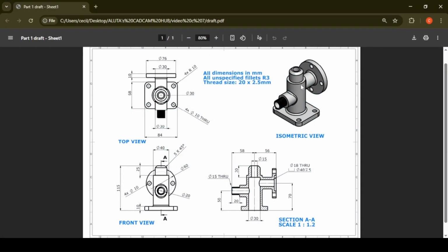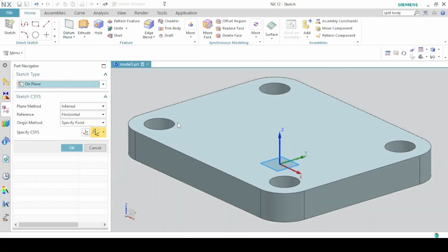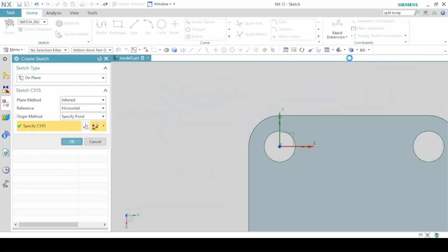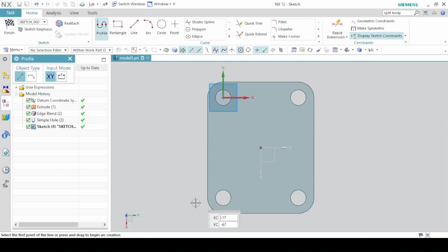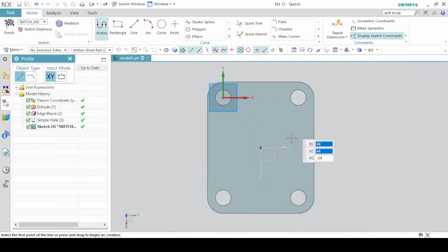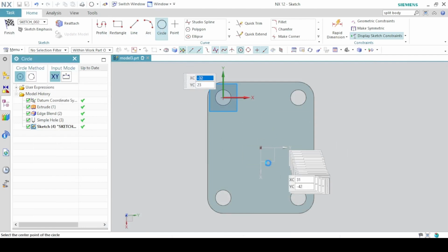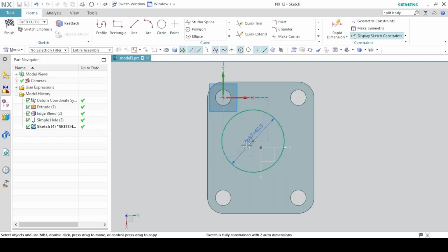Next we add this middle cylinder and the top one as well. So extrude, because we are adding material. Sketch section on this face. So draw a circle of diameter 40 millimeters, and it should be in the absolute center of the block. Let's place it in the center. So click on this center, locate the center of this vertical line. It should be on the same horizontal line.